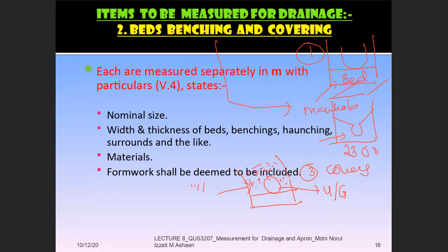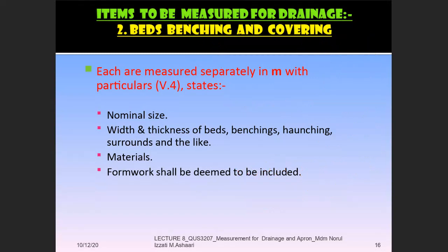In your case, you can only see the beds. So how do you measure the bed? You can measure it by referring to the length on plan. So the answer is actually similar to the length on plan when you measure the trench excavation. So make sure you get the length on plan correct before you go for the next item, because you can take the length from the first item. Okay, this is the length on plan.